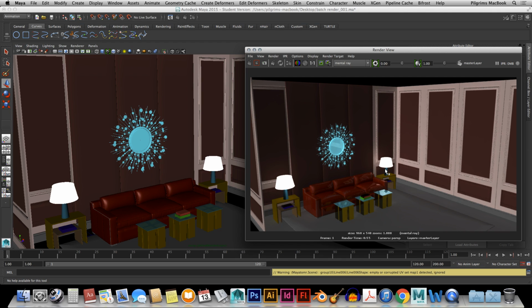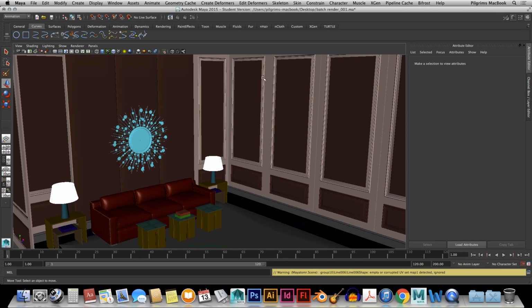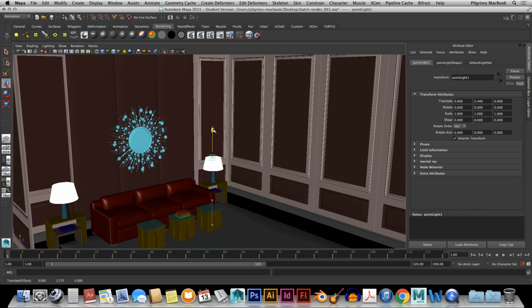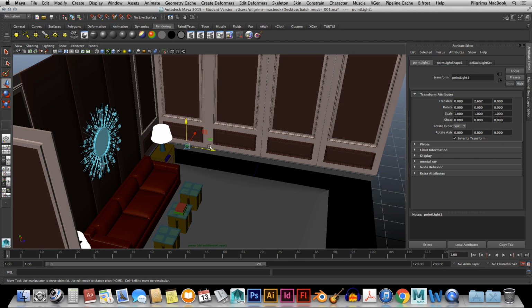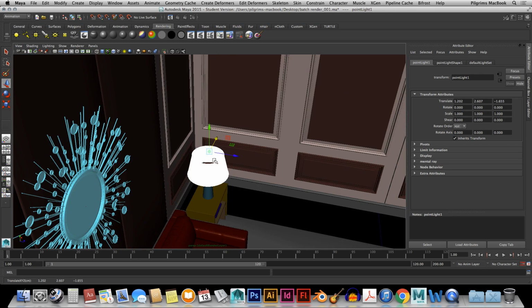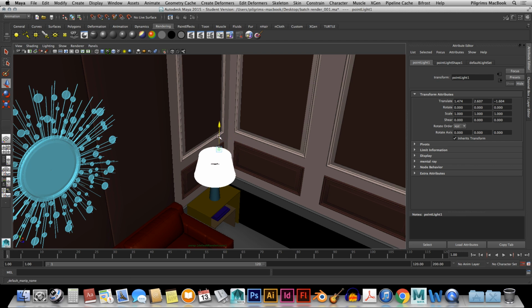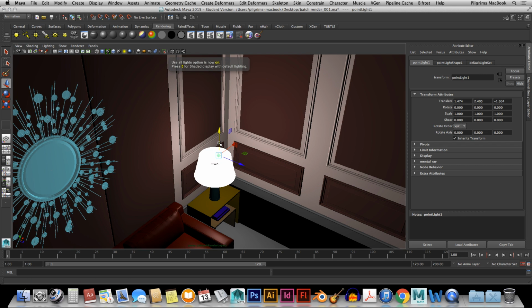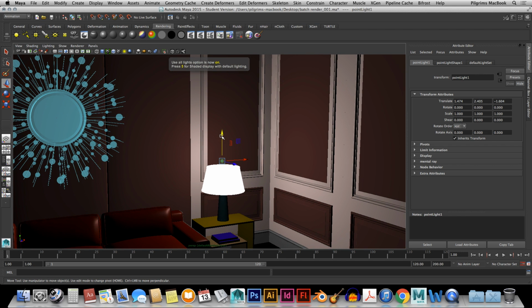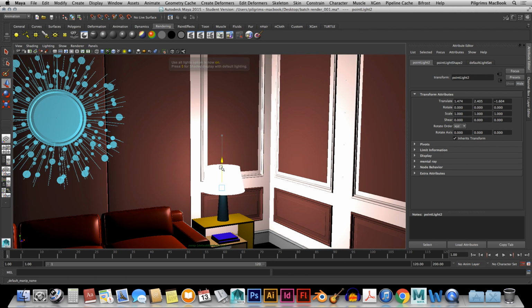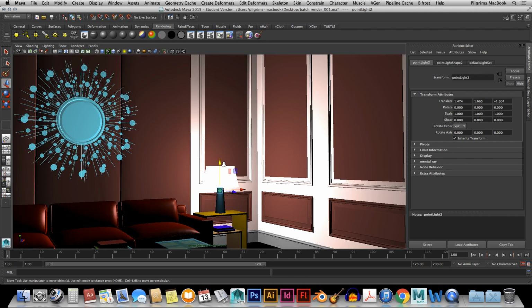And now what else we needed, we will use some sort of lights. So we'll go to the rendering tab, and here we have the point light. We'll create the point light, and move it a little bit upward and somehow here. Okay, just press F and see. Quite well. If I press 7, I definitely can see. Control D again, and we'll move it somehow here. Let's have a look.